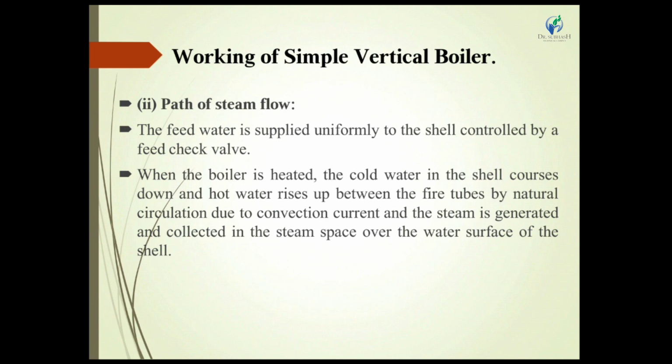What is natural circulation? If you put water in a bowl and heat it, the centrally heated water comes to the top side of the bowl, and the cold water at the side goes to the bottom. It is due to the density difference or temperature difference. Due to the density difference, the hot water goes up and the cold water goes down, and it makes a normal circulation of the water. That is what we call natural circulation. The Cochran boiler is also a natural circulation boiler.